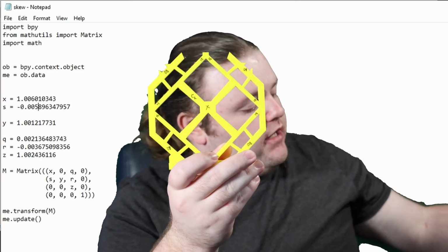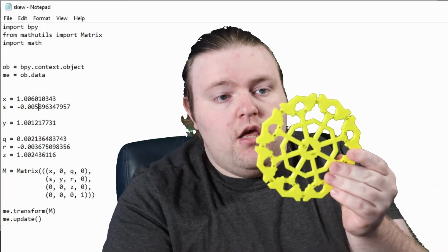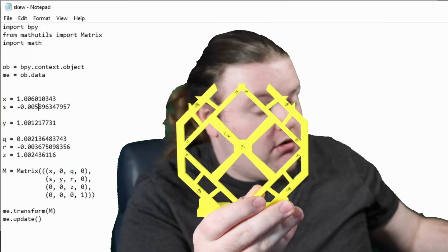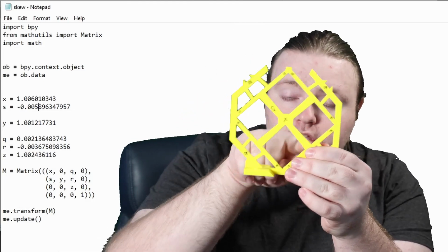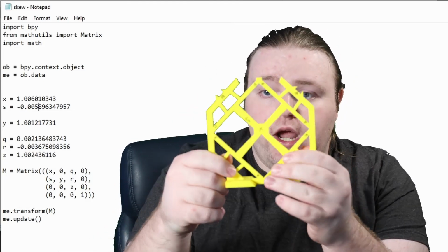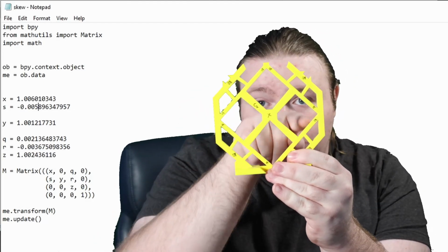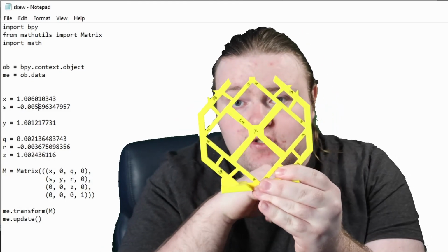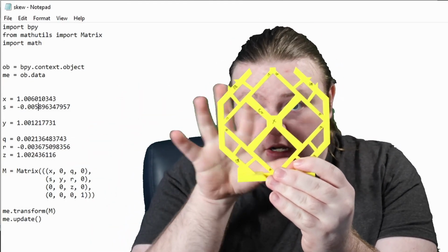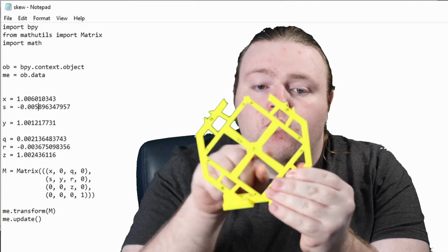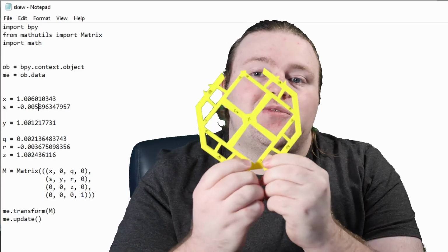Part of the reason that I went with the octagon is that this octagon can print with no supports. And you'll see, we're very clearly seeing this rotated square. The other square, the standard square, doesn't fit. So that's a problem because it would need support, right? That's why it doesn't work. So we only get this one square. So we lose precision, but at least we can print these.